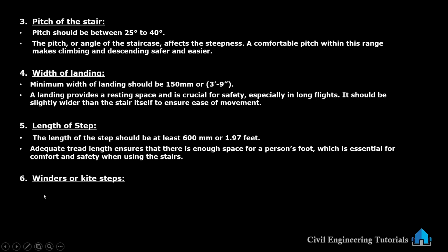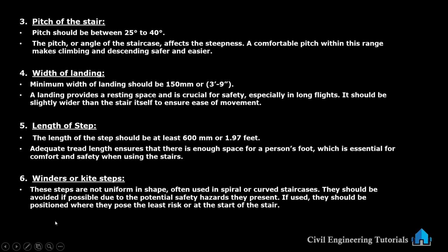Next, winders or kite steps. These steps are not uniform in shape, often used in spiral or curved staircases. They should be avoided if possible due to the potential safety hazards they present. If used, they should be positioned where they pose the least risk or at the start of the stair.